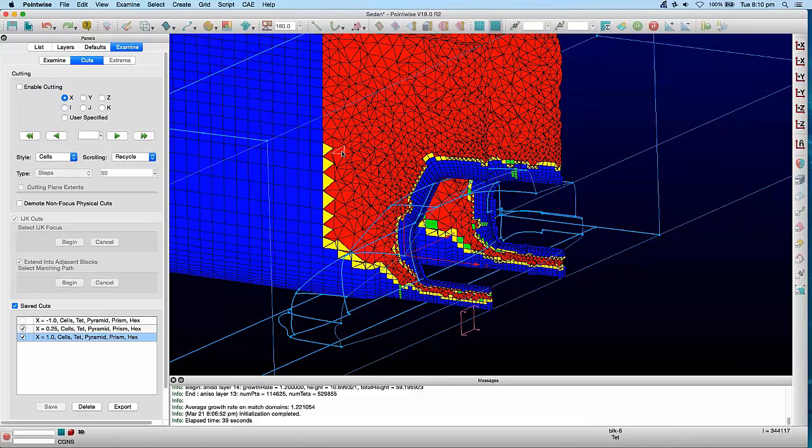And I know for a fact that when I first met Scott, they were doing about 300 million cell meshes. Yep, because they were running with a Y plus around 1. Subsequently they've switched to running about a Y plus of 30 with a wall function. And that allows them to bring the mesh down to about 60 million. Yep, around 60 million. Realistically there's probably not a lot of difference between the results. So going from 300 million down to 60 million, it's the way things go.